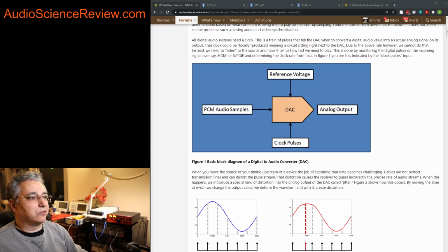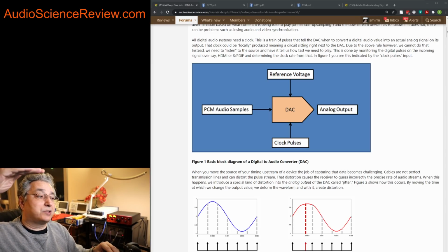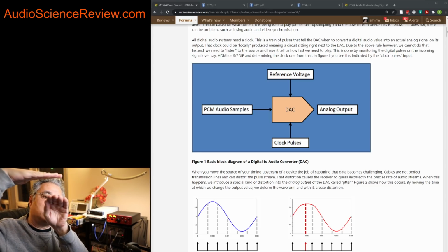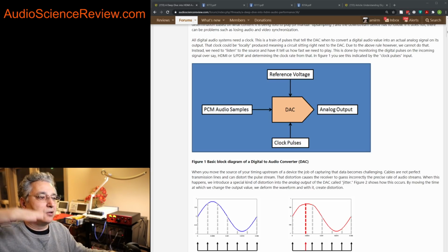and the analog comes out. What the DAC does is that it also has what is called reference voltage, which I won't talk about much today, but it can look like jitter contribution. In that it takes this reference voltage, let's say it's 3 volts, and then it divides it by the steps that you tell it. So this sets the sort of maximum value, and then when you give it a digital sample, you're saying, give me a ratio relative to that.